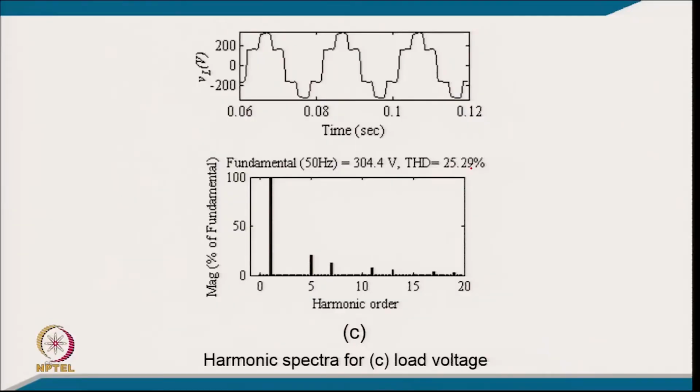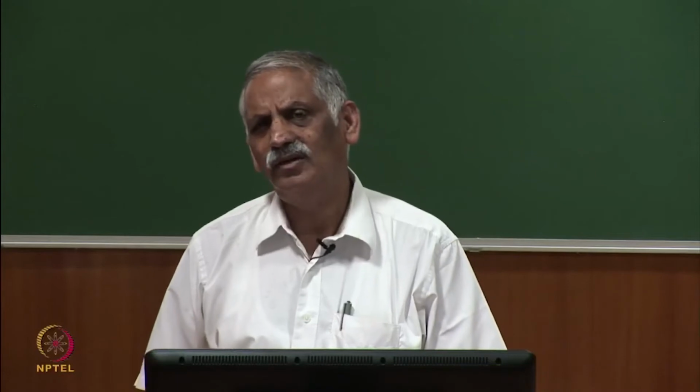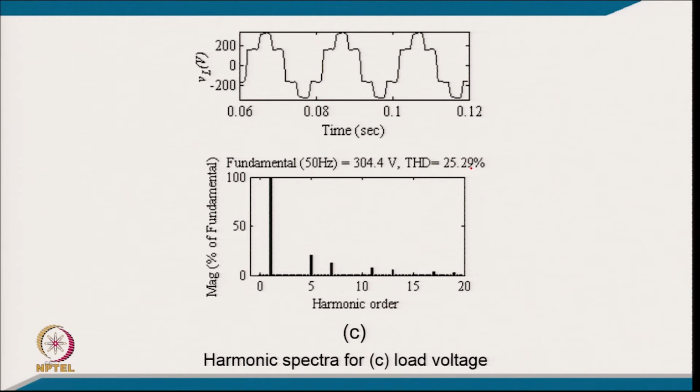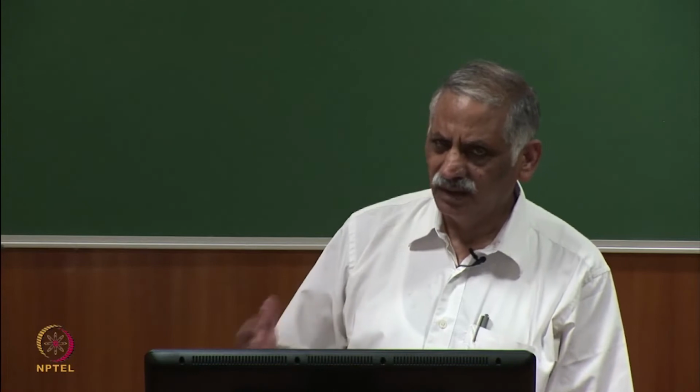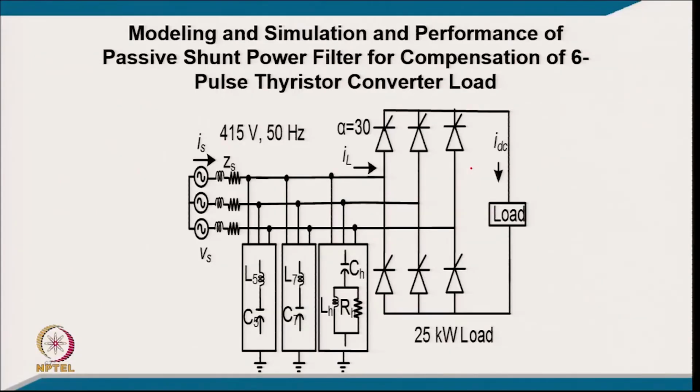So, you can correlate this; it covers reasonably the concepts of power electronics in all these circuits, because it is a power electronic circuit, and it covers the THD at the load voltage as well. But this is not going to affect the load in any way, because the capacitor is now charging more effectively by all 3 phases. Earlier it was charging hardly, with only 2 phases, current flowing from one phase and returning through another, and sometimes the current was not flowing at all. So now you will find the ripple on the capacitor voltage is also less. That is the benefit.